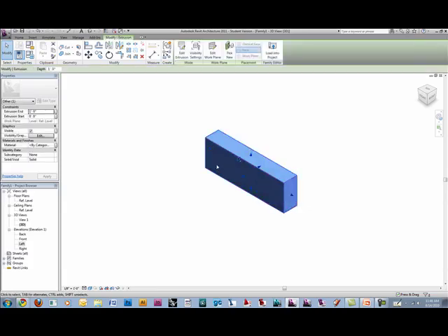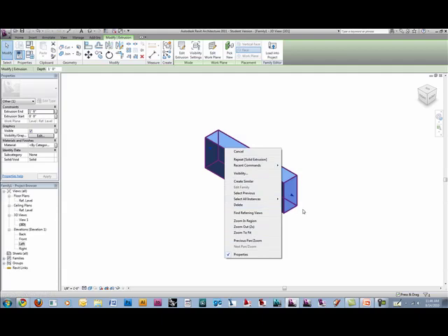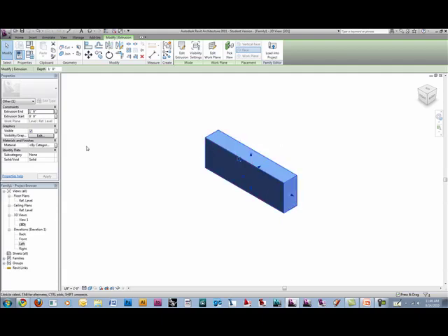So to add a material or a finish, in 2009 and 2010 it was a lot different. Now that this properties box is open, it's a little bit easier. It's just in a weirder spot because you're so used to right clicking on stuff to label it, and there is no label for this one. Now you just go over here and say material, and you can change the material right here by clicking the little etc button, but there's a new button off to the right of it. It's like a double etc button.